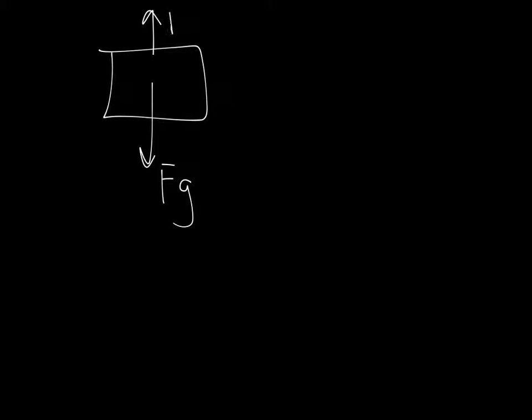All right, buoyancy problems. You want to consider several things. First, did I go over the steps with you guys or no? Start by drawing a free body diagram, FBD. Draw a free body diagram. I'm telling you now, there was one homework problem where the submarine was accelerating. I'm not going to have problems where it's moving. So either it's going to be submerged underwater or floating on top of the water. In both of those scenarios, you've got the weight pulling down and buoyancy pushing up.